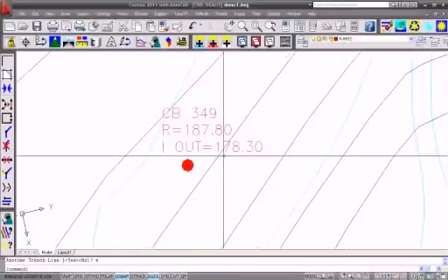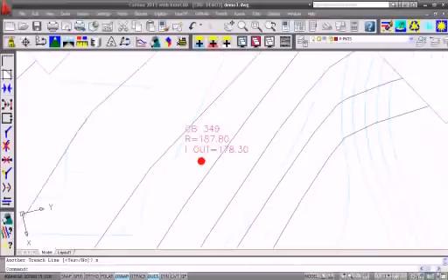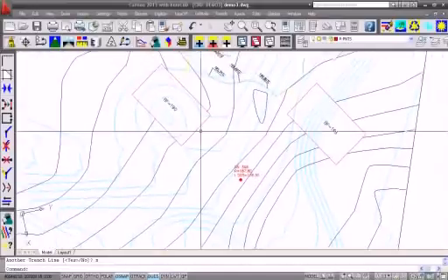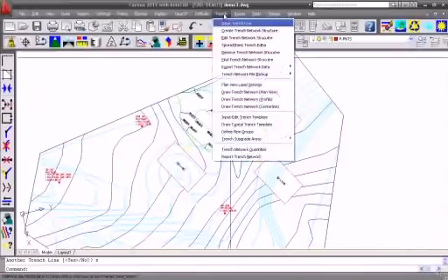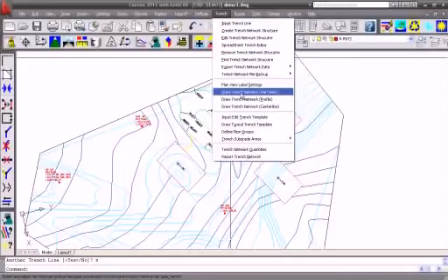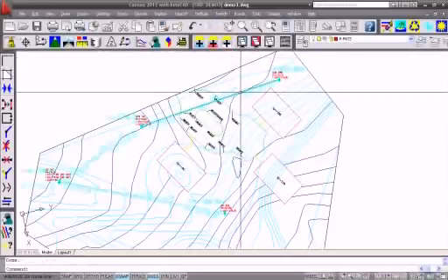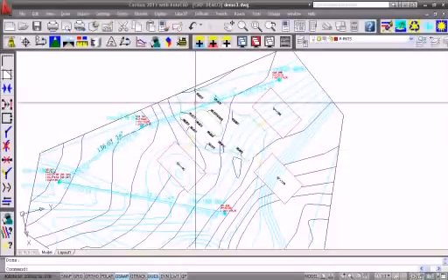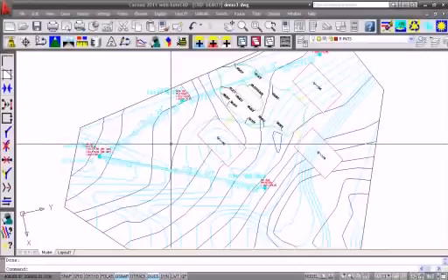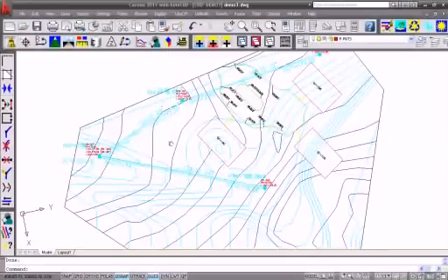No. All right, and now under trench, I can say draw trench network in the plan view, and I can see how those are connected up. It gives me the linear footage between the two, or between all the manholes.